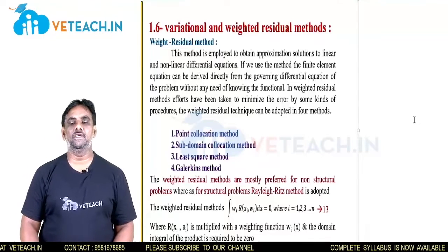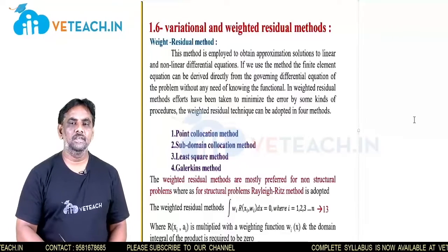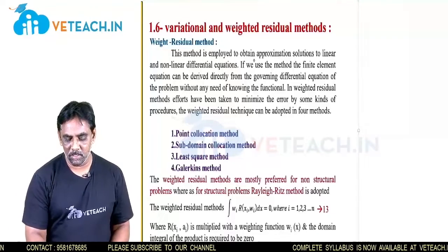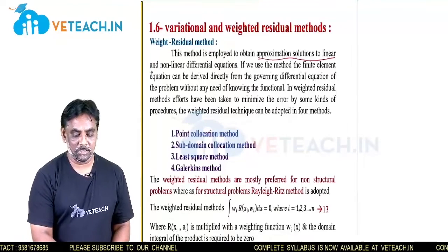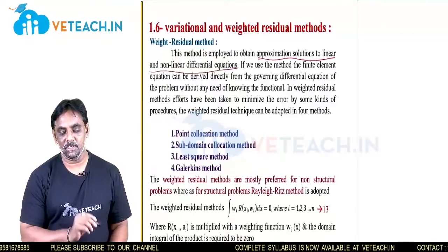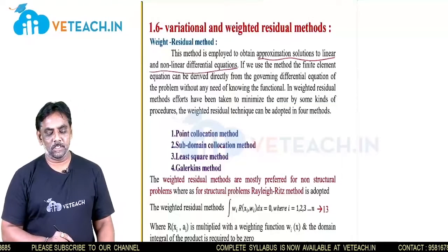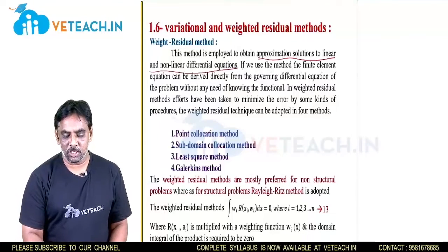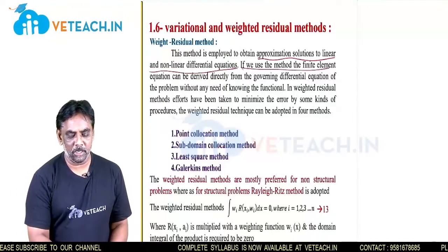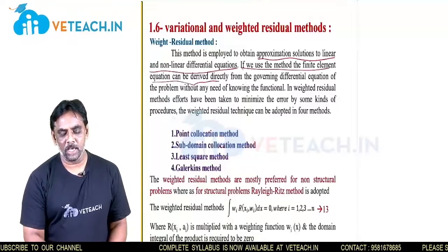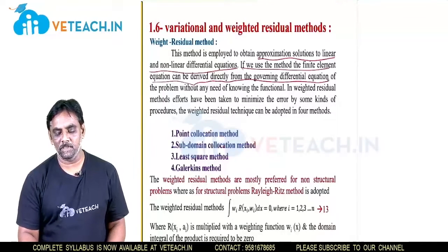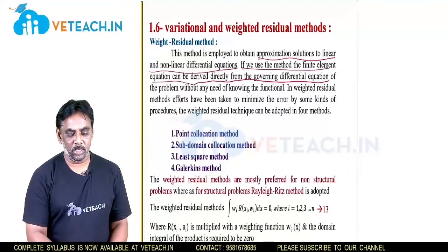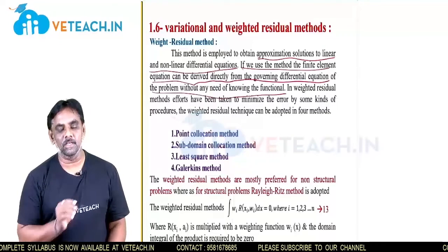So, what is the meaning of these weighted residual methods? Generally, this method is applied to get an approximate solution to linear as well as non-linear differential equations, and in this case we use this method in the finite element equation, which can be derived directly from the governing differential equation without any need of knowing the functional.